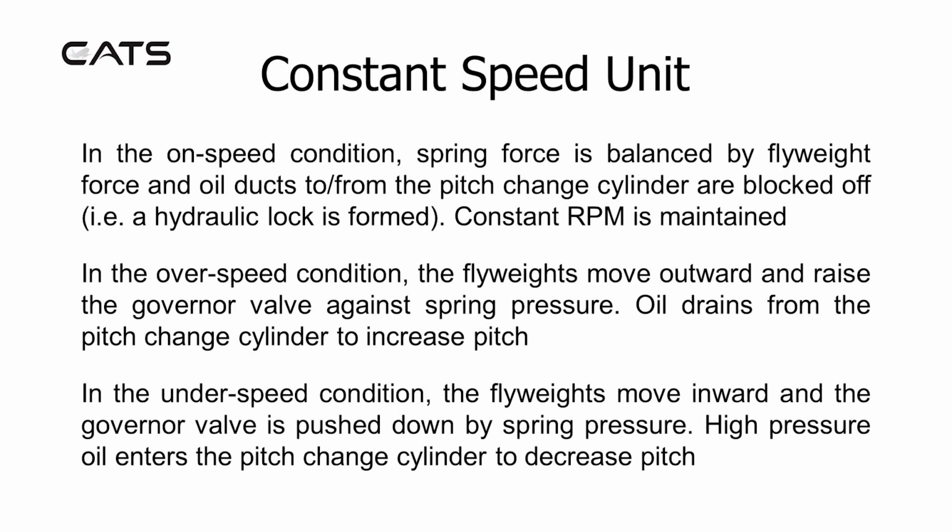In the on-speed condition, spring force is balanced by flyweight force, and oil ducts to or from the pitch change cylinder are blocked off, i.e. a hydraulic lock is formed. Constant RPM is maintained. In the overspeed condition, the flyweights move outwards and raise the governor valve against spring pressure.